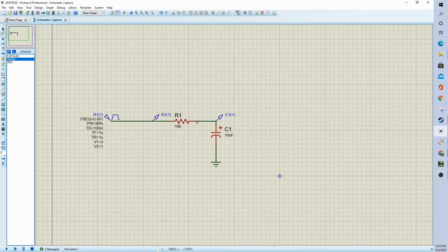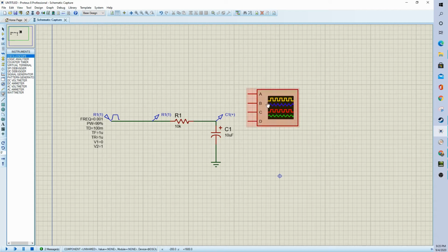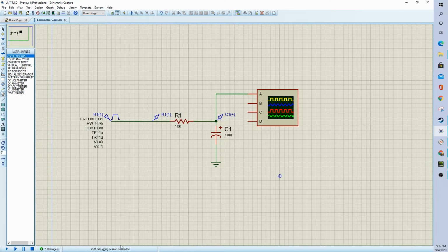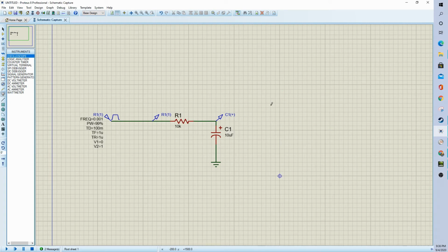What we expect to see is that when it turns on, this capacitor will charge up, and as the current goes down, the voltage will increase, and we'd be able to take a look at it. If we just run the simulation, we can see that it does actually ramp up, but it's hard to see what's happening. The conventional thing would be to hook up an oscilloscope and capture that, but it's really hard to capture. It doesn't simulate well enough. In this case, it's maybe too slow, or it could be too fast. The transient event is way outside our ability to capture it with conventional methods.